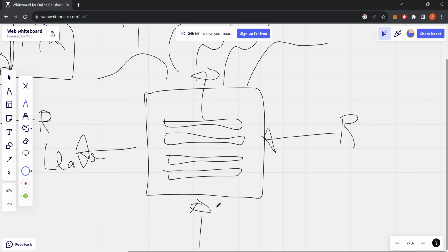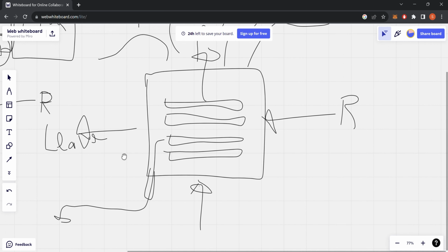So these pipes are cold. And what happens when the pipes are cold is anytime you run warm air that has some humidity onto a cold surface, you get condensation. So while this is happening, all this air is actually condensing water onto the outside of these lines, which is why the inside of your house has to have a drain, because it's going to collect that water and run it outside the house and dump it somewhere. So that's why you got to have that drain.